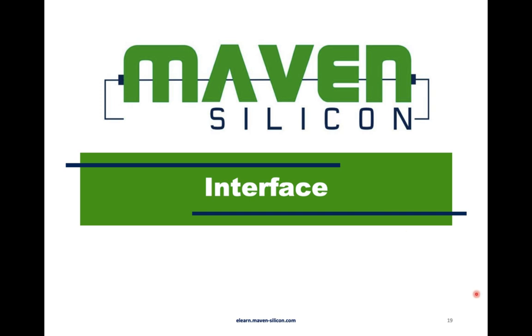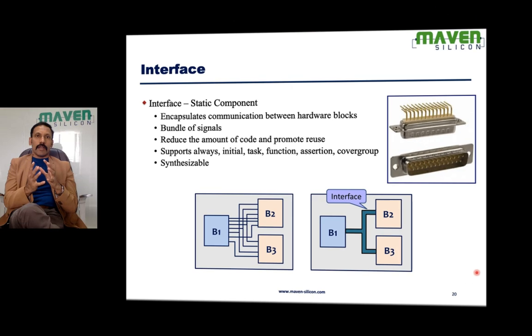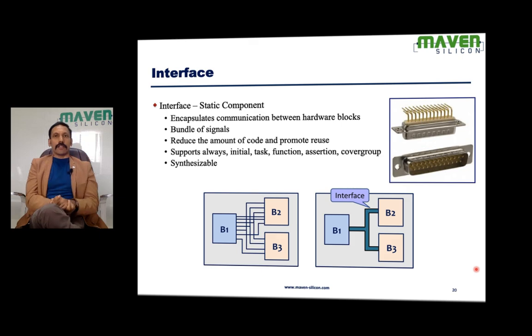Interface. Interface is nothing but a bunch of ports. So in SystemVerilog, you can define a component called interface, and within the interface you can define all the ports. Conceptually, this is how an interface works.